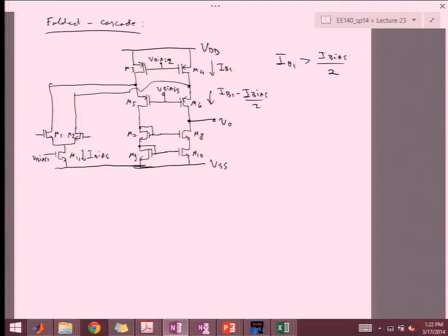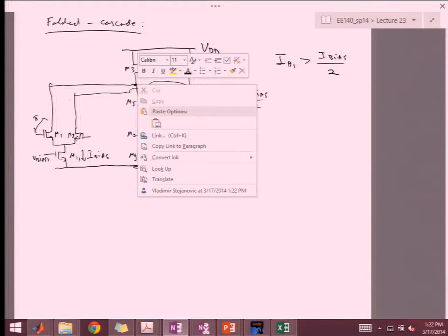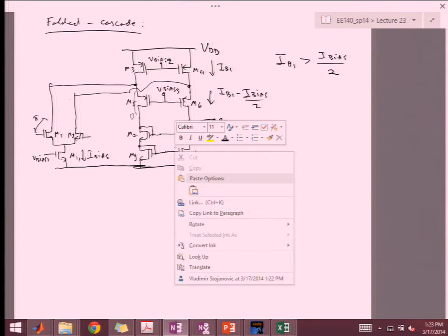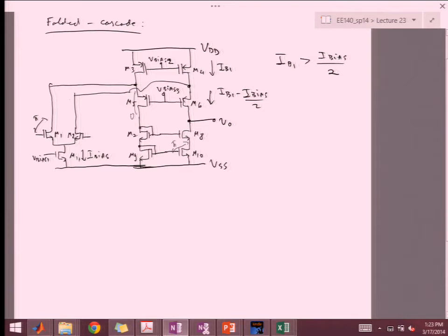So you take the input and you go, how do I get from input to the output, right? I have to traverse some gate drain connections and some source drain connections, right? So let's pick this one. I go gate drain, so I'm getting pi. Now I'm over here. Now here I go source drain. Right, so that's a 0. Then this is just the resistor, right? So I'm just developing that voltage on this one. So then I'm driving this guy, right? So from here to here, it's pi. And then again, up here, it's 0, and I'm at the output.